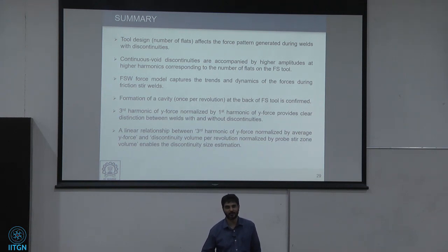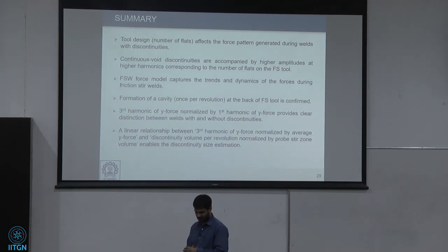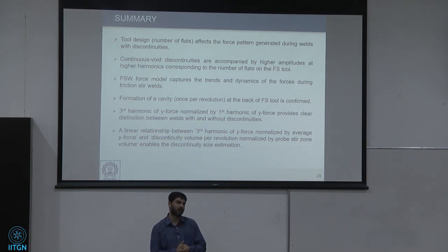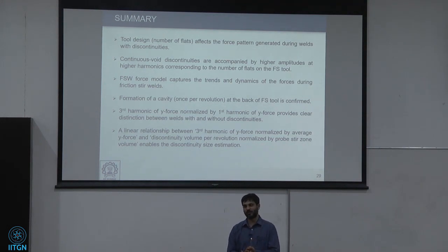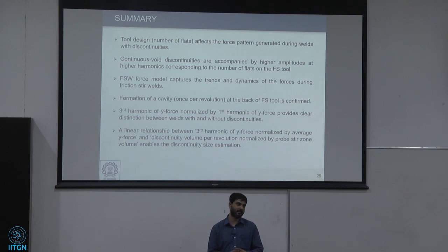So to wrap up the talk, a bunch of points to be summarized, concluding remarks. Forces are inherently tied very closely to the material movement. The cyclic nature or periodicity of the material movement very clearly reflects in the periodicity of the forces, and hence force signatures can be used for measuring or detecting the formation of defects during the welds.